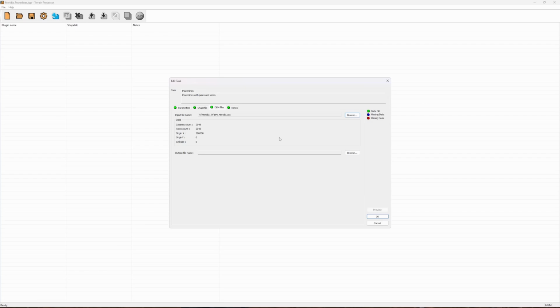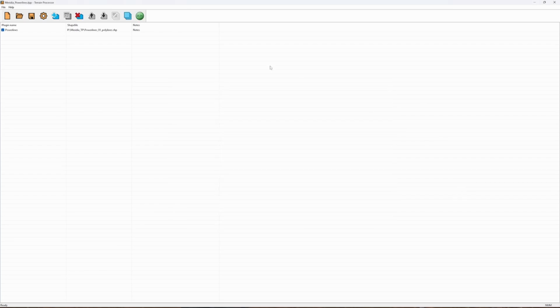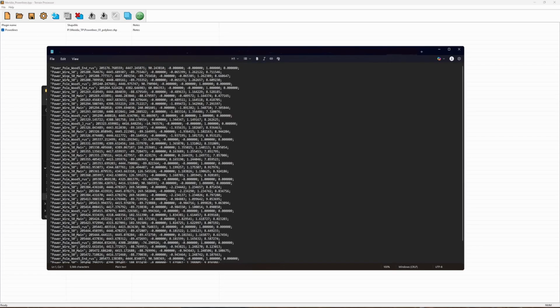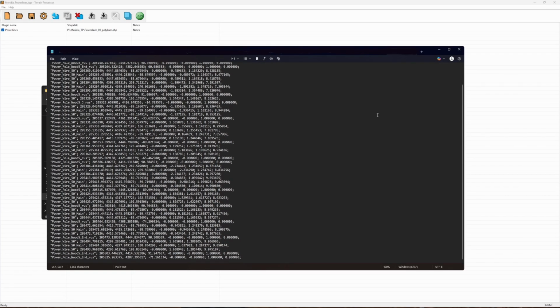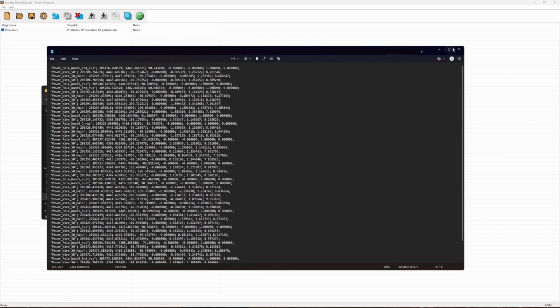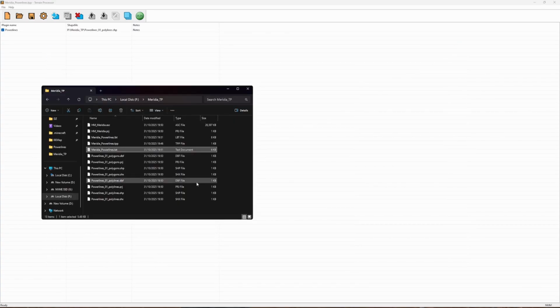As you see, I've got it here. Click OK, then click Run. It will give you a text file once it's done and tell you how many objects it's made. You can quickly come and check it. It should have power pole end and so on, and then wires. For pole wood 5, it should have 3 wires in between it, or a certain amount, but it should be fine.